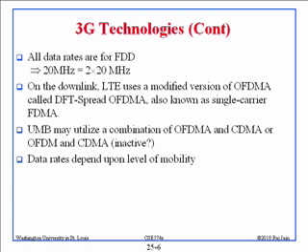Understood? Second thing is, in LTE, they use a special form of OFDMA, which is called DFT spread OFDMA, also known as single carrier OFDMA, and I will talk more detail about that later on.